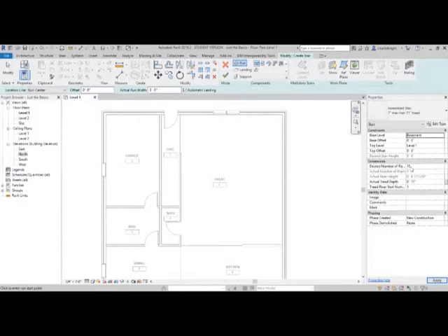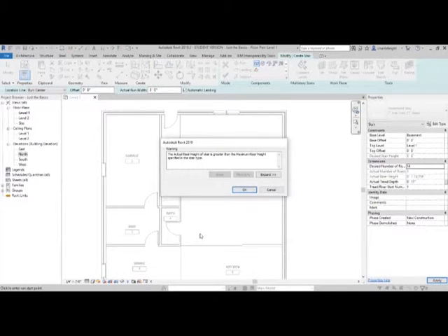And I've told it, well, I want 15 risers, and those 15 risers are going to be at about 6 inches, 6 inches and a half, a little bit. It gets very, very accurate. I could tell it, well, I don't want that many treads. Can we try to knock it down to 14? And when you do that, it goes back and it does the calculation based off of the number of steps that you have in that 7-11 ratio.